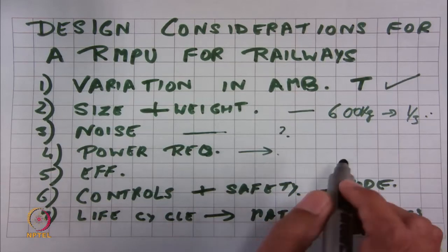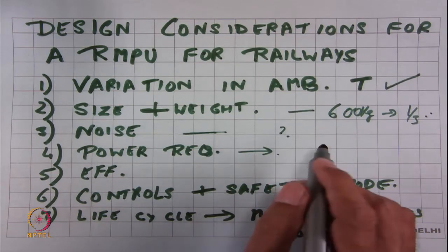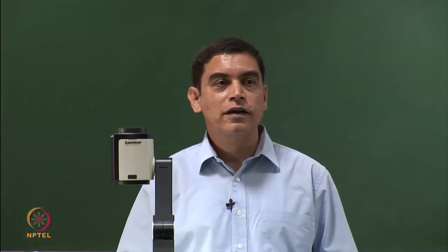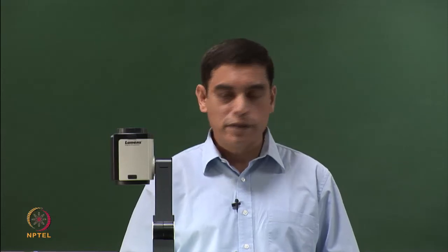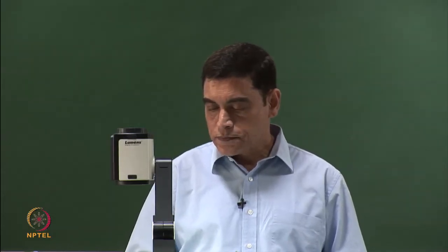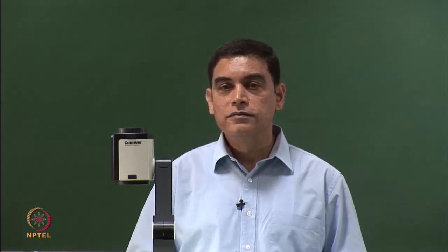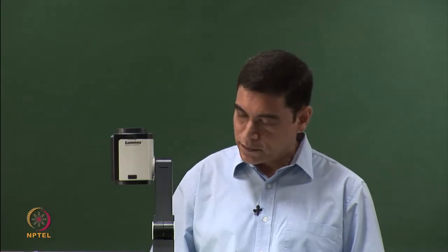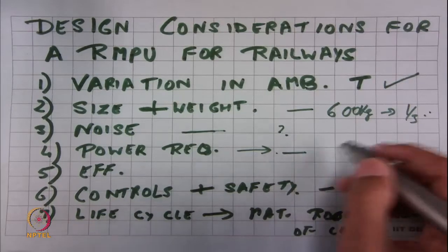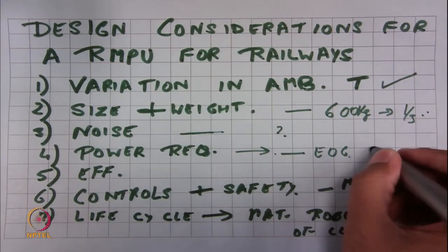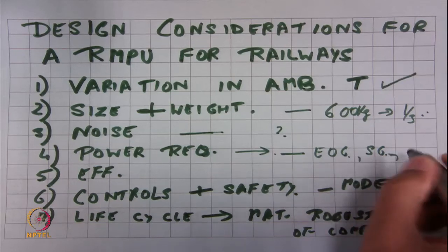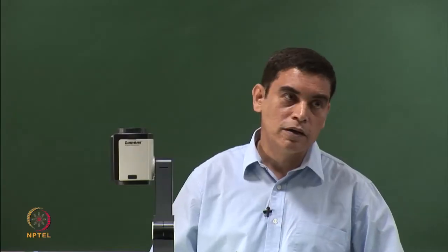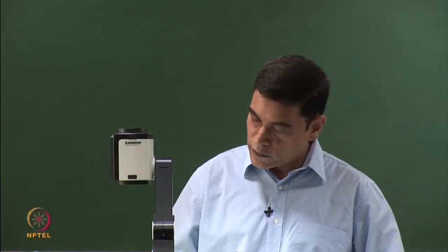Power requirement, yeah. This is something I missed. Between different manufacturers supplying the motors for the condenser fan and also the transformer used for the control application, there was a need to revalidate things using temperature rise with pulse width modulated power supply. So while the units worked fine for end-on generation, there was something called self-generating coaches which required some changes. But finally this was addressed. So the robustness level of the motors and the control equipment was altered so that they don't overheat with the modified waveform.